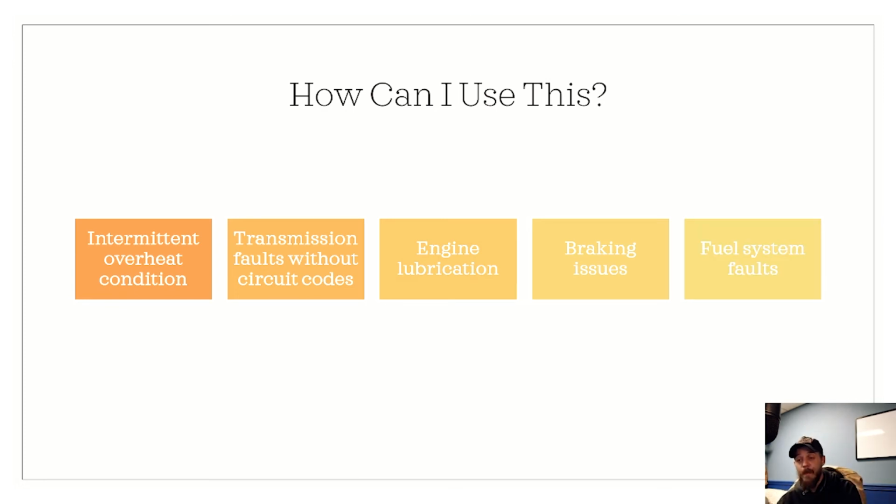Fuel systems. So if a lot of you aren't familiar with diesel fuel systems, one that's been around for a long time, the venerable 7.3 Power Stroke is one I love using as an example. Used HEUI systems, hydraulic electric unit injection. So they take low pressure oil from the engine that feeds into a high pressure oil pump, which then uses force